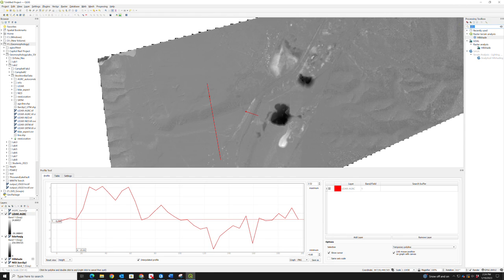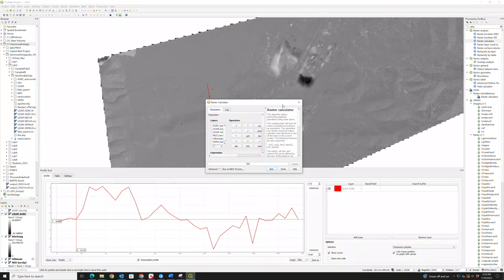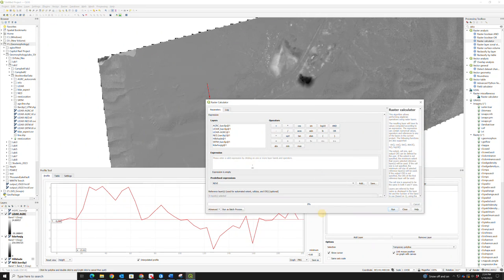And if you wanted to do that yourself in ArcGIS, it's called raster calculator. Let's see if we can find a calculator here. So raster analysis, raster calculator, boom. Yeah, so we can open this up a bit more, right? We could say, I want to subtract, I want to take the SRTM away from that.